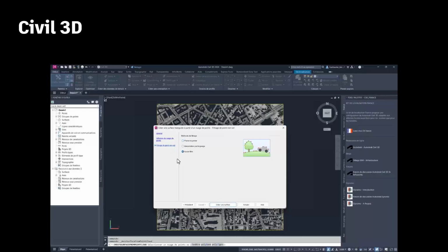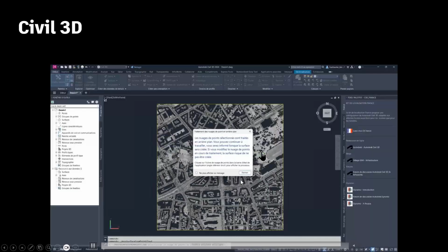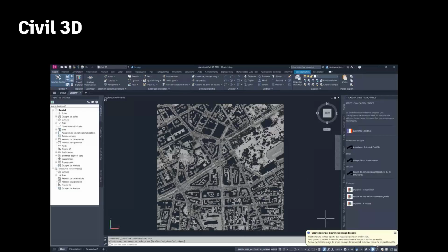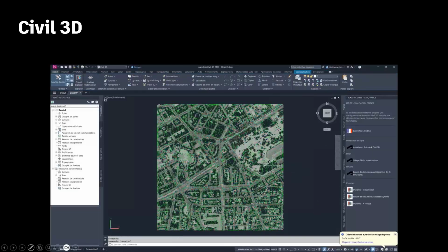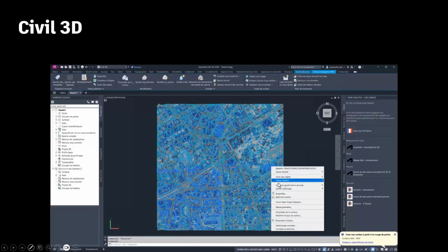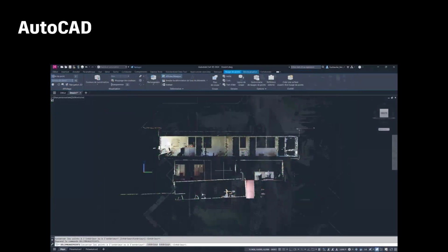So when you do create that point cloud, you're using that no filter option, because all you have are ground points. So we don't have to mess around with that interpolation and get sort of a close, accurate representation of the surface, because all we're using is the ground points. It's going to be accurate based on that point cloud. So make sure you take advantage of the automatic classification.